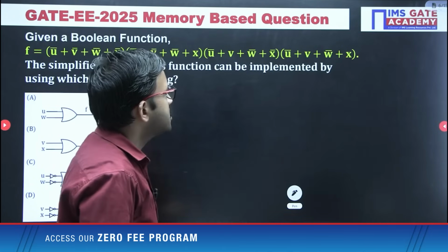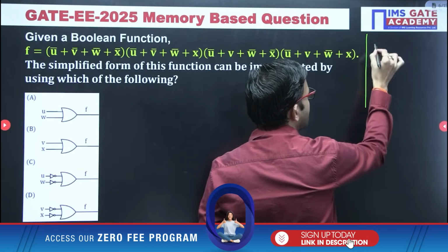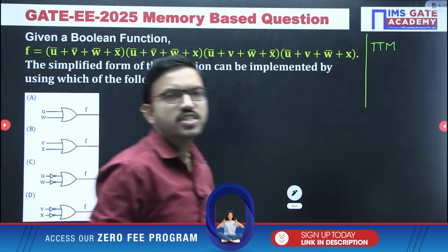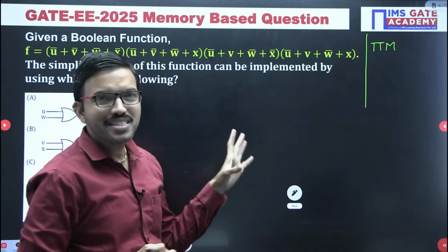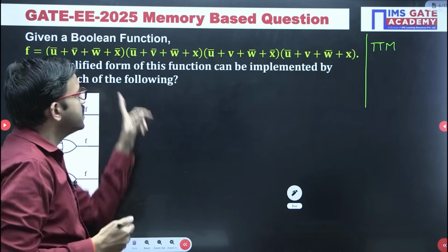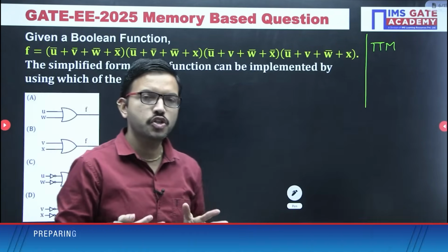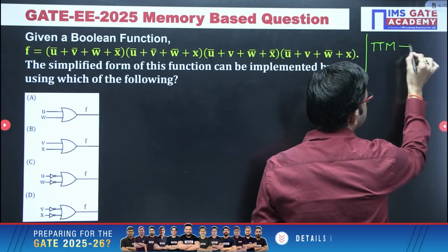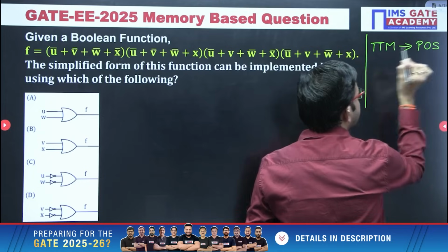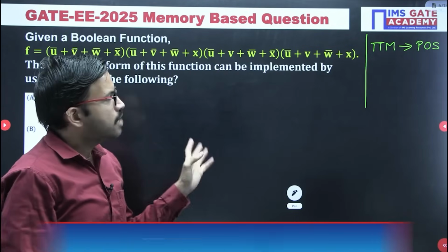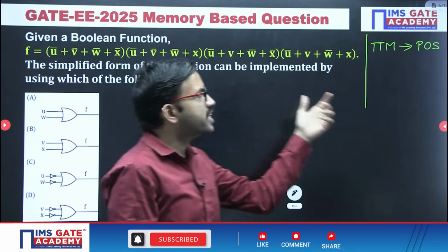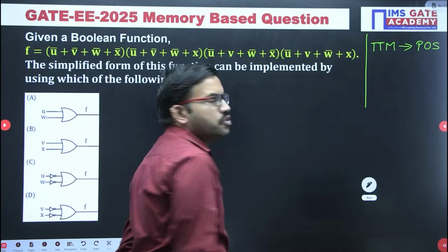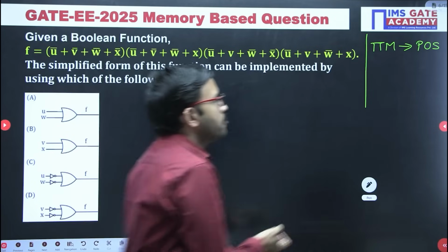Okay. See, for this particular question, many of you might have solved this question. Since the given function is pi capital M, you might have considered a 4 variable K-map, and in the respective max term positions you might have put zeros, and then you have done the grouping. Of course, definitely from there also you will be getting the same answer. Okay, so whatever the given pi capital M is there, with the help of K-map, when you do the simplification, you are getting one POS form in general. Okay, fine. See, that is one method you can do it. Okay, by using K-map you can do it.